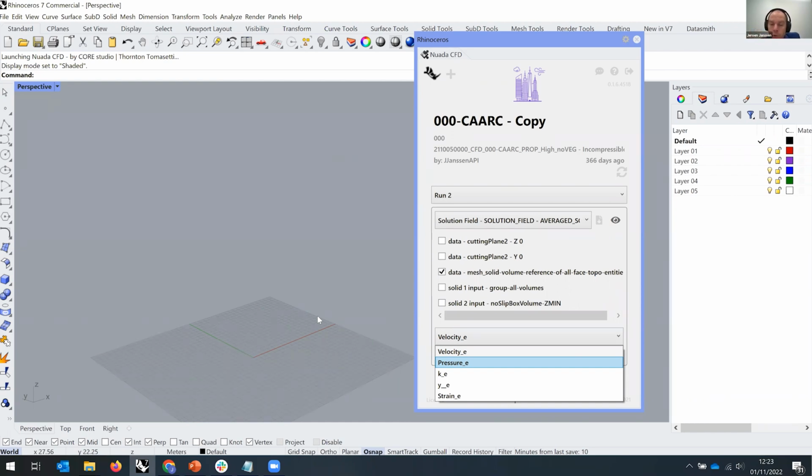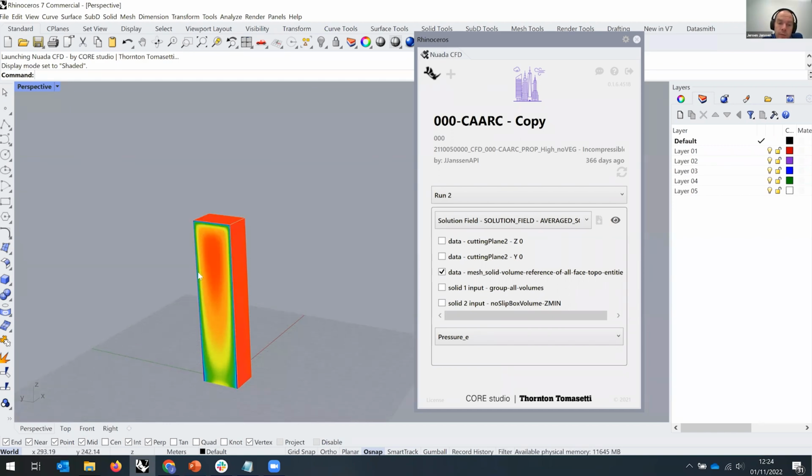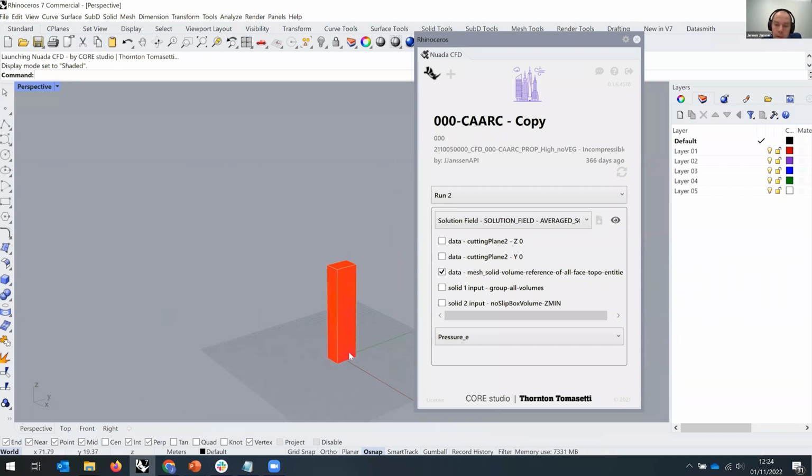And that's also on the roadmap before the end of the year, to use this to find pressure distributions and your base moments and shears to get into structural analysis. But this is your pressure distribution, and it's pretty typical for a building like that. High zone of pressure on that kind of two-thirds of the height, low pressures around the corners and the back. Again, we need to work on the color gradient because it's red on both sides, so that's not really helpful, because then it's relatively low at the back, which you would expect as well.